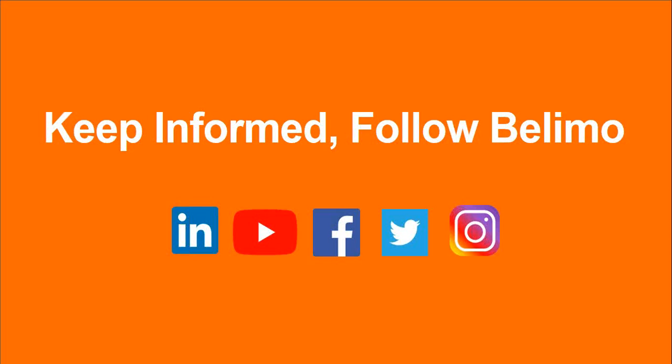Okay. Next question, is the energy valve a product to solve the low delta T syndrome, or is it only a product or tool to help diagnose that there is a problem? It can be used for both. One of the benefits of the energy valve, particularly the web server, is that it shows where the current delta T is and also captures that delta T in the data file.